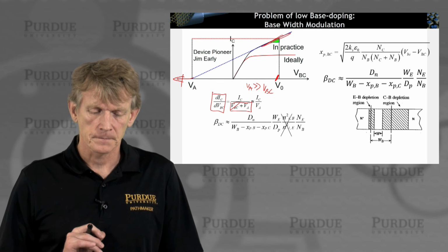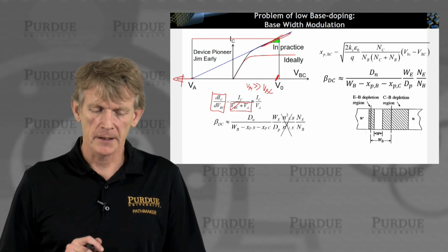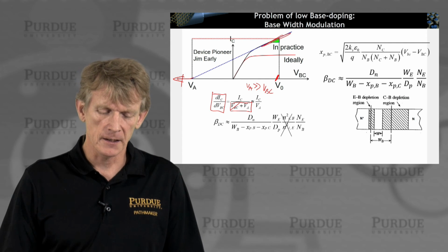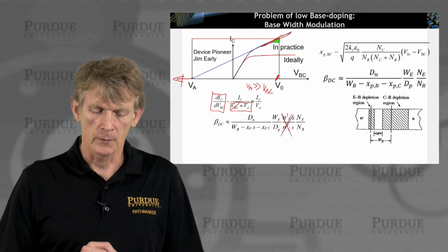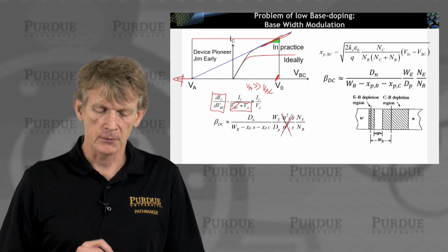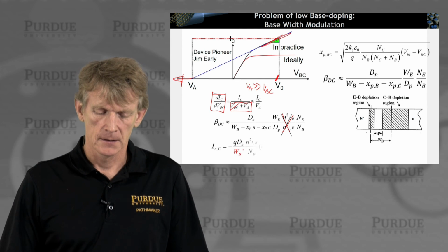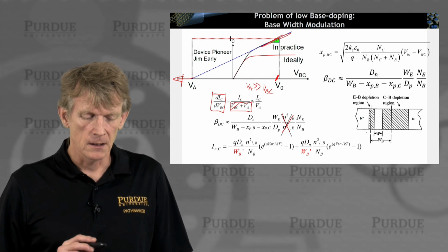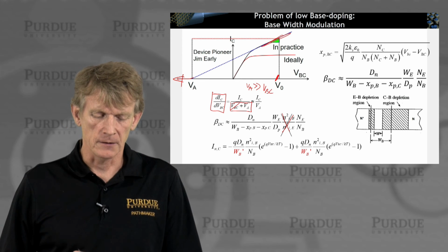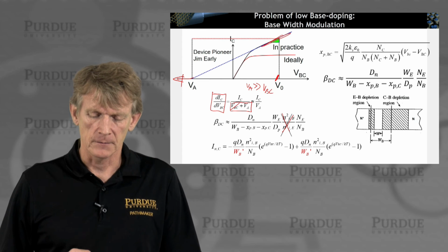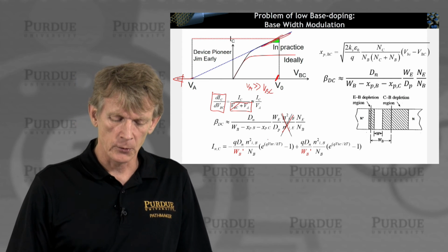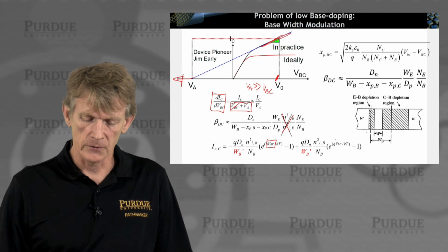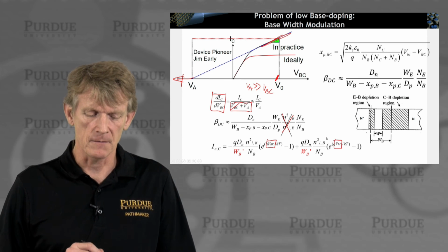All right. Now we're going to calculate beta DC again. We're going to drop out the term NI, and we have the same expression as what we have up there. And we write down the current again for the collector. Okay, again we have two components, the forward bias component VBE and the reverse bias component VBC.